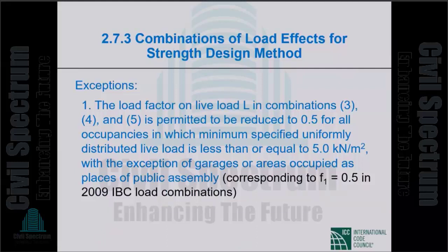Dead loads cause bending moments at the support section of a beam. Live loads also cause bending moments. Wind also causes bending moments. We combine the bending moments, the load effects. So we call them load combinations, but they are combinations of load effects.